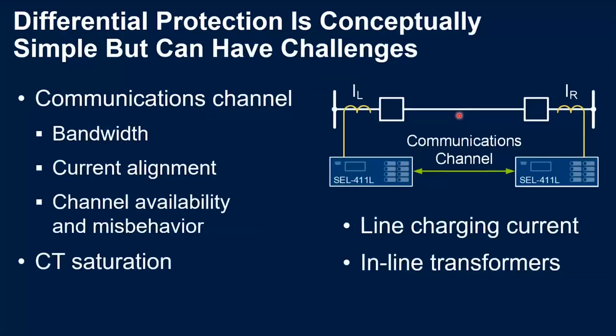But when we're talking about differential protection for lines, each terminal of the line will be separated by a distance, which can be a large distance. So in differential schemes for lines, we will have two relays, as you can see in the image. And we'll need to place a communications channel for them to communicate the current information from both terminals.